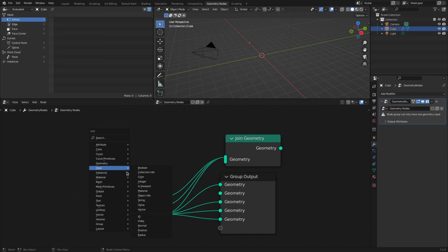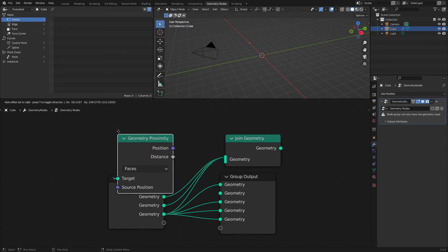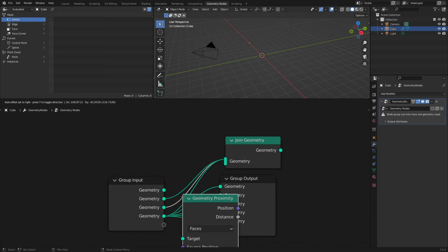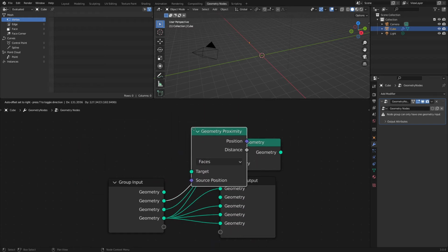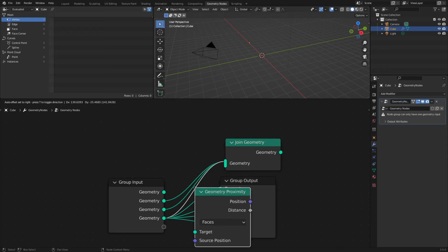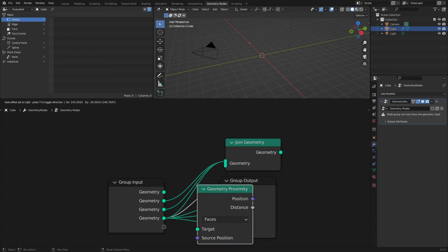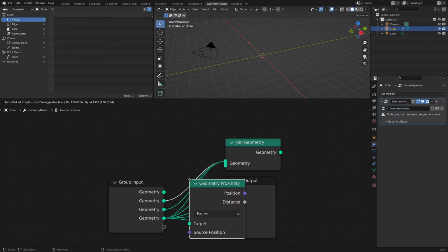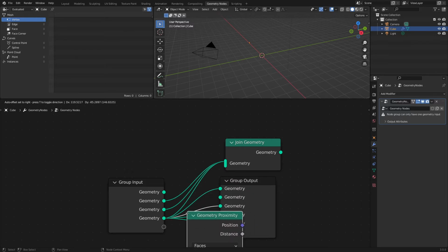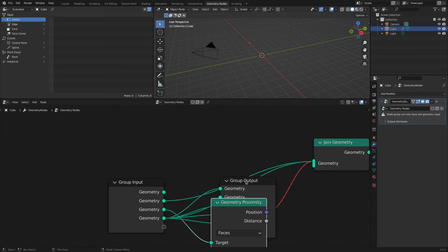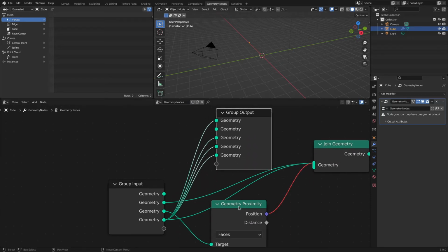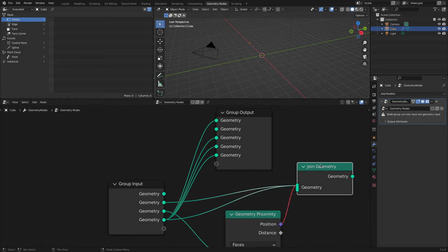And as we've talked about previously, any node without any input or output connections, if you simply drop it onto a link, see how as I'm hovering over the links, they're highlighting. First one, second one, third one, they highlight as I'm hovering over different links. Using that as a guide, I can then drop it onto the link I want to insert the node into. So let's say I want to insert it here. I just click it and it will self-insert. And then of course you're going to want to rearrange to make it look a little more readable.